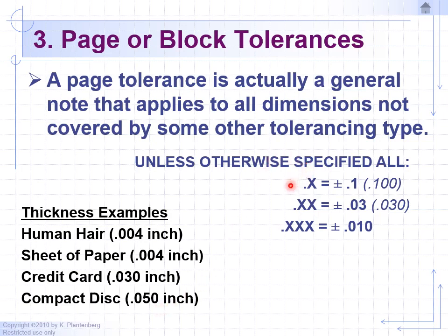So once again, if you give a length of, let's say, 1 inch, and it's only 1 decimal place, in other words, it's 1.0 inches, you're telling the machine shop to go into the title block. Again, you're not providing a tolerance directly on the dimension, so they have to look in the title block, and they'll say, okay, 1.0, 1 decimal place, then we can be off by plus or minus 0.1 inches.